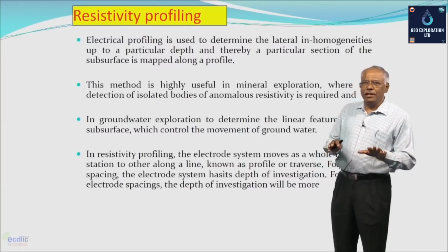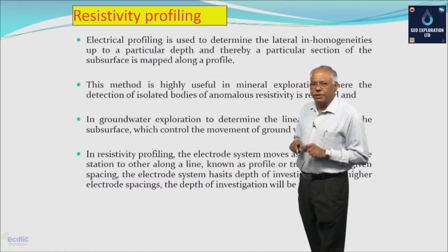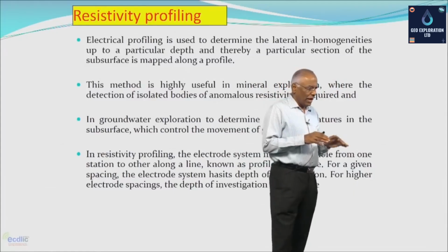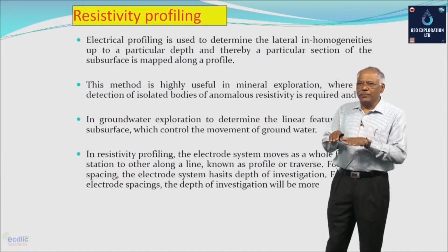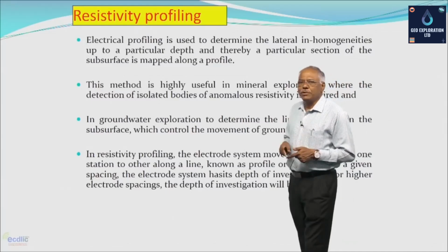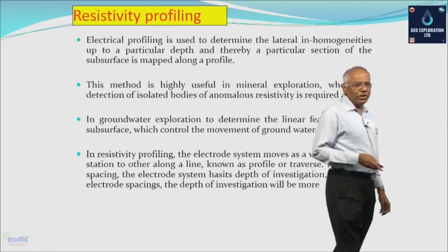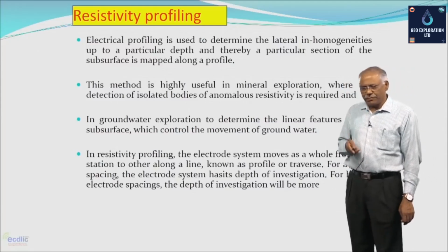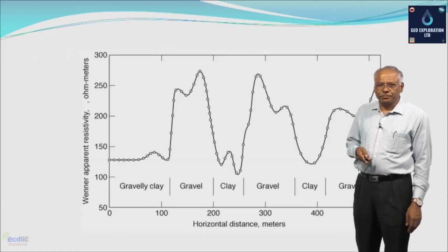In profiling at a constant depth, measurements are made to locate the lowest resistivity spot. That is what is done in the profiling. And at the lowest resistivity spot, or resistivity low in a given field, then you can make the measurements by another technique which is known as vertical electrical sounding. Resistivity profiling and sounding are two typical terms that are used in terms of exploration for the groundwater. And this is what is typically the profiling.